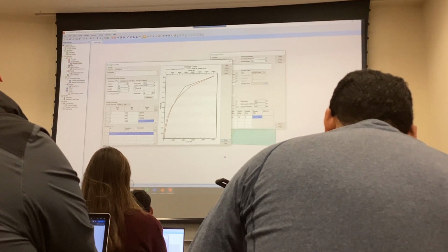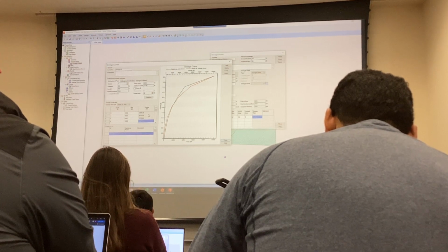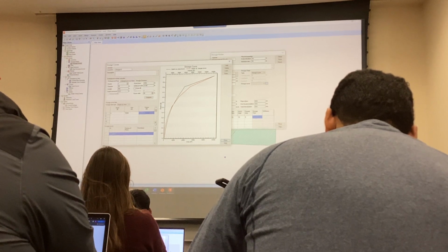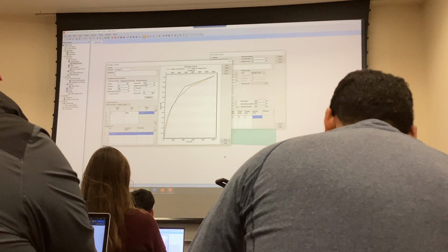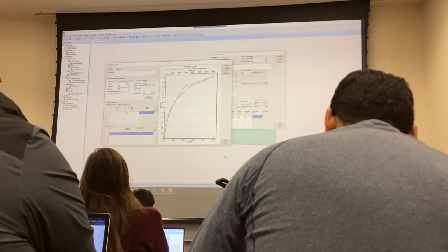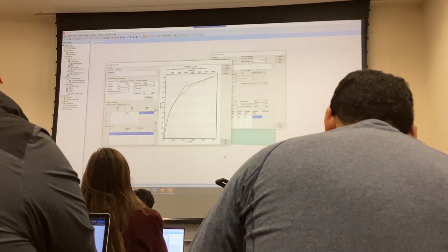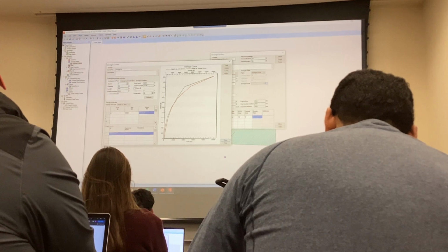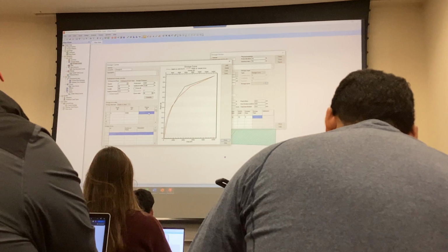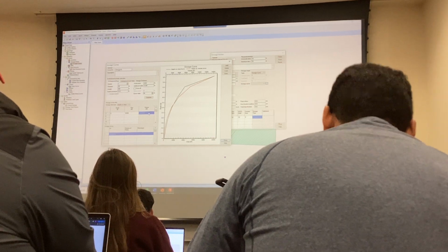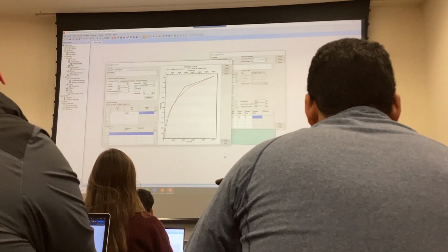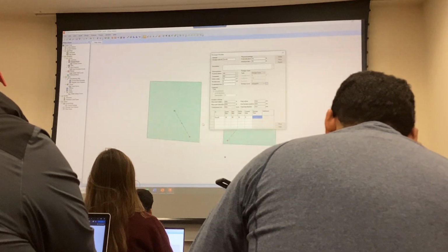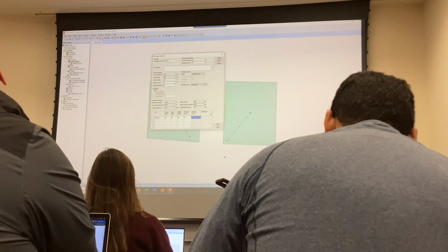But this volume here is actually a cumulative volume, so it is always going to be increasing until you get the maximum volume. So another way to check if you input this correctly is to check the volume inside your detention basin by making a manual calculation versus what comes out at the very end. Okay. So with that, I'm going to say this is okay. I'm going to accept this profile.